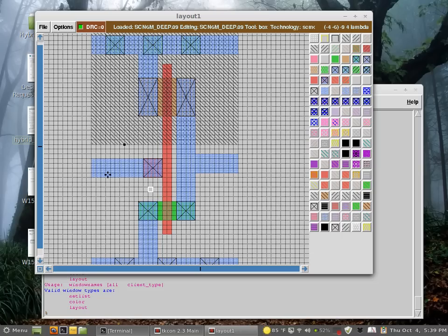but if you want to see which layer is connected to which, place your cursor over some area like that and press S. Now S, the first time you press it, it will select the most obvious rectangle under it. If you press it a second time, it will go through all the connections, through all the contacts. So here it went through the contact and it selected my other connection, which is a polysilicon. So now I know my metal here is successfully connected to the polysilicon.